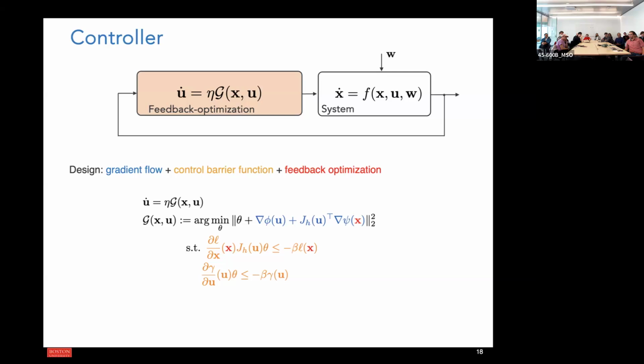The main takeaway is the following. If I want to run this algorithm as is, it will be open loop, with no interconnection with the system, and I need to know W. In a power system, W is the power consumed or generated by non-controllable assets. I don't want to monitor them. So by replacing h with the measurement of Q and W, I can get away with the need of measuring W. This is the main benefit of this trick.